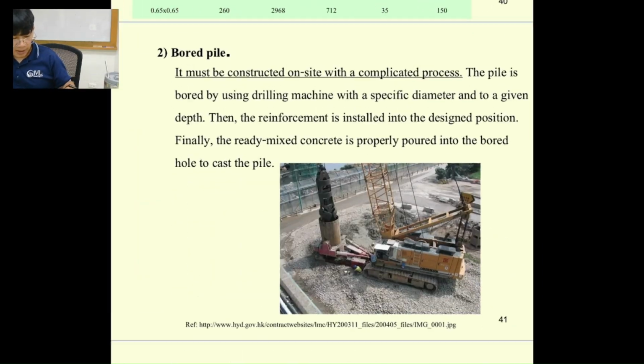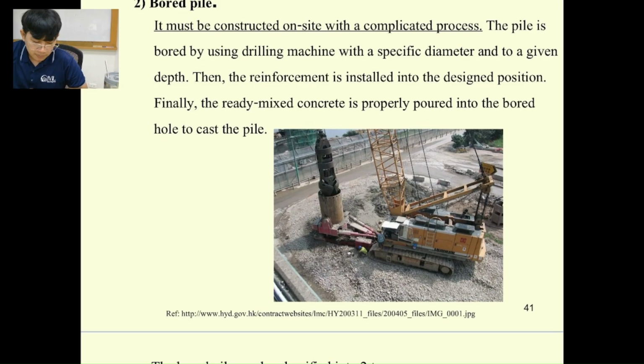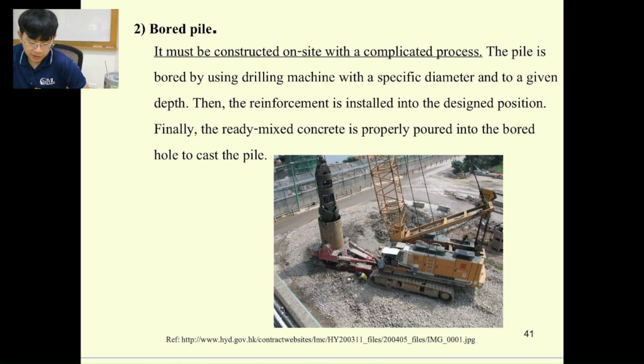If you move to the bore pile, it's a lot different from the driven pile. With the driven pile, you use the pile and push it under the ground like this. But for the bore pile, it's another story, because you need to make a hole like this and get the soil out first, then put some reinforcement and pour the concrete in. This one we call the bore pile.